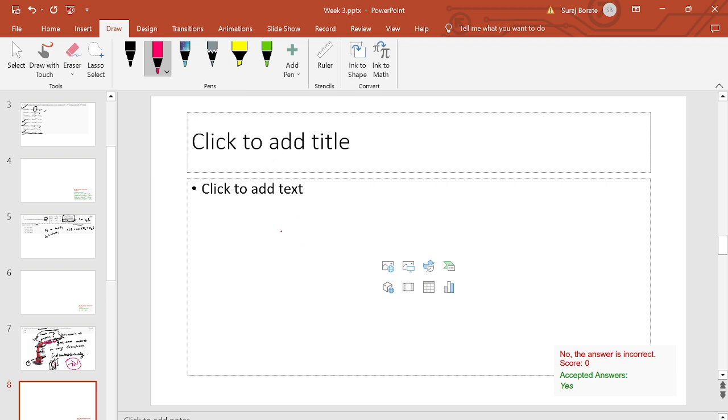Okay, so the wrist, the front part is like this. There is a motor over here. If you open that arm, it will look like this. There will be a motor over here. Then there will be a pulley, and there will be a belt. Okay, and there will be some bearing over here, and this belt will rotate this link.